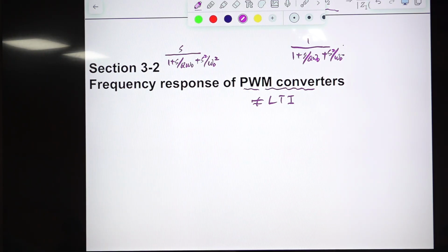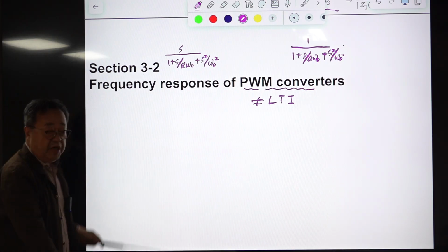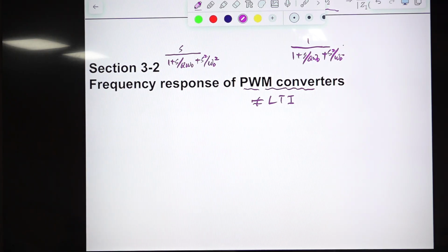So this one starts from the differentiation, so it will start with a plus 1 slope, and the slope will be lowered by 2, so it becomes like that. This is a plus 1 slope, and this is a minus slope, and this is the resonant frequency omega naught, and there is a peaking, something like this.